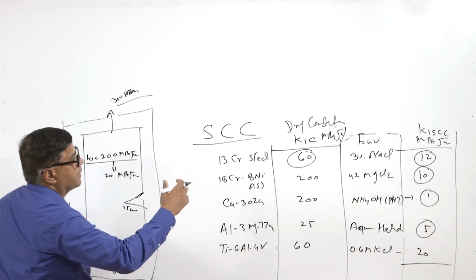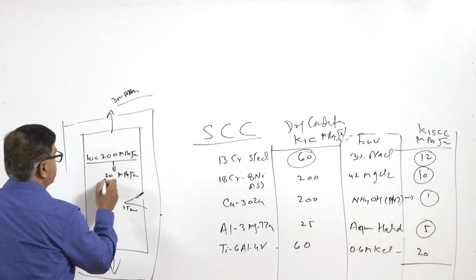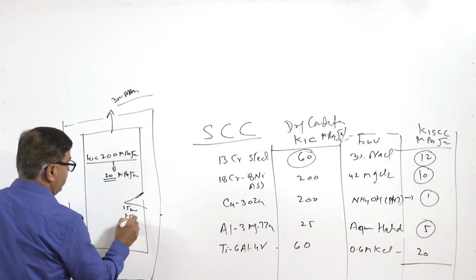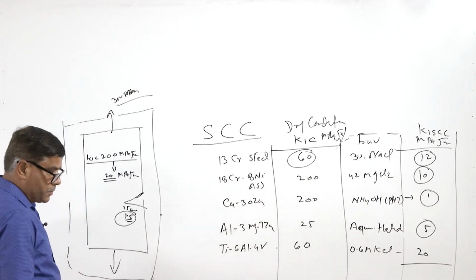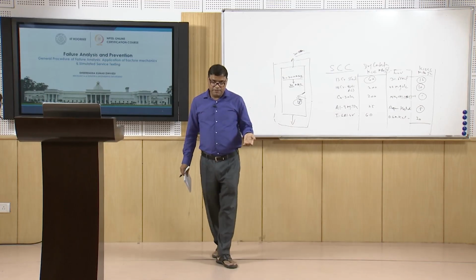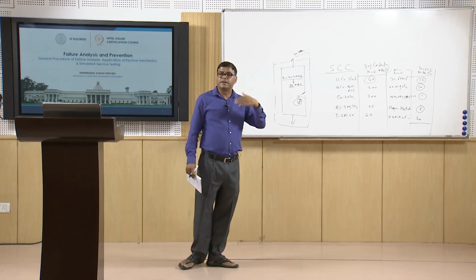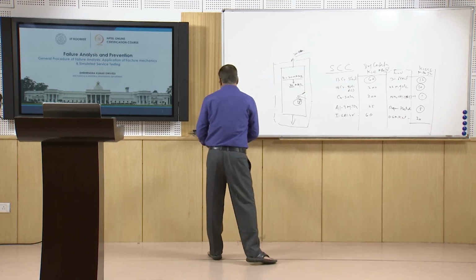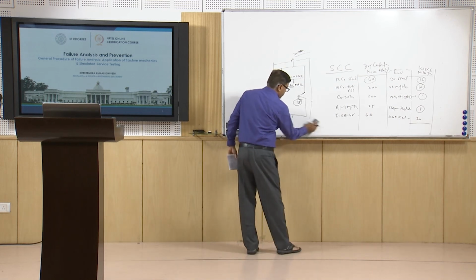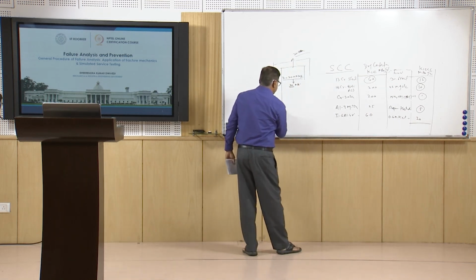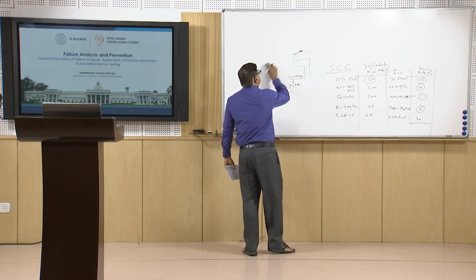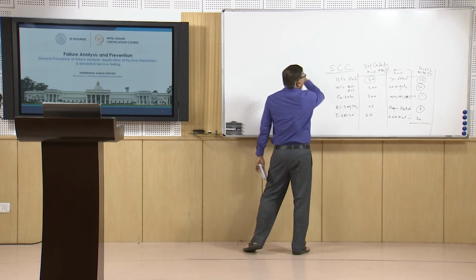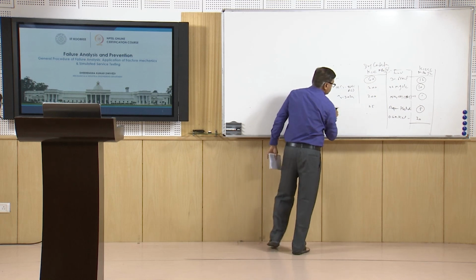But when it is exposed to corrosion conditions under tensile stresses, it gets reduced by 10 times. So, in this case the tolerable size of the crack will be reduced to 1.5 mm. So, with the change of the environment, there will be a significant reduction in the tolerable size of the crack, or indirectly a significant reduction in the maximum stress which it can accommodate. So, it is important to consider the fracture toughness, especially in that particular environment, when it is expected that the component can fail under stress corrosion conditions.